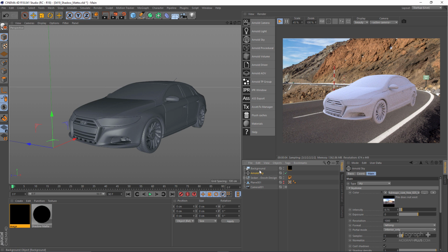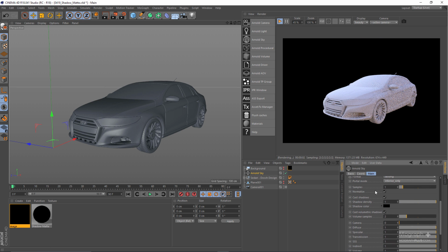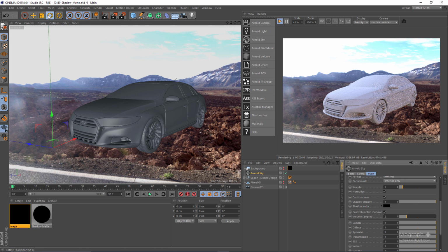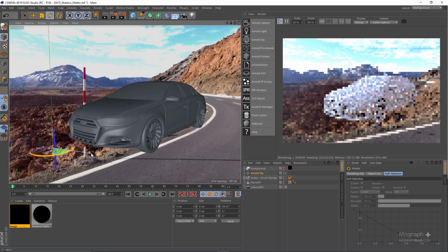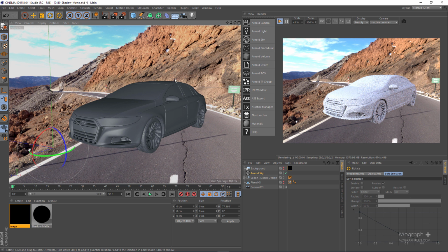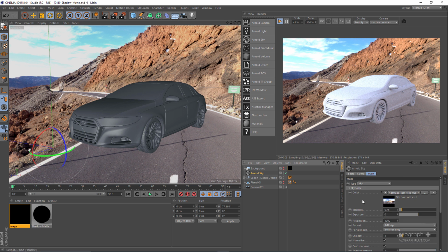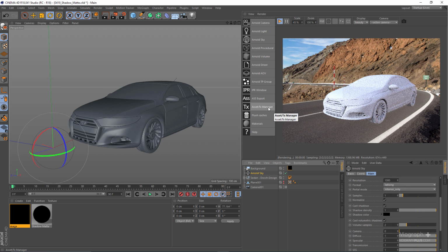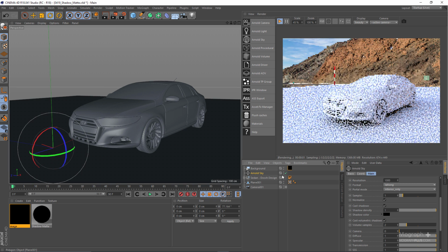So what we can do is to simply hide this background. You can see the backplate here, so I can simply hide the background, and for the time being let's increase the camera contribution to 1 again. And if I start rotating my HDRI, you can see now we have a very close match. You can see the backplate that we have was taken from this view. So now we have our HDRI map and our background at the same view. So we can select our Arnold sky, zero out the camera contribution again, and turn on the background. Also, let me unhide the plane that we have.